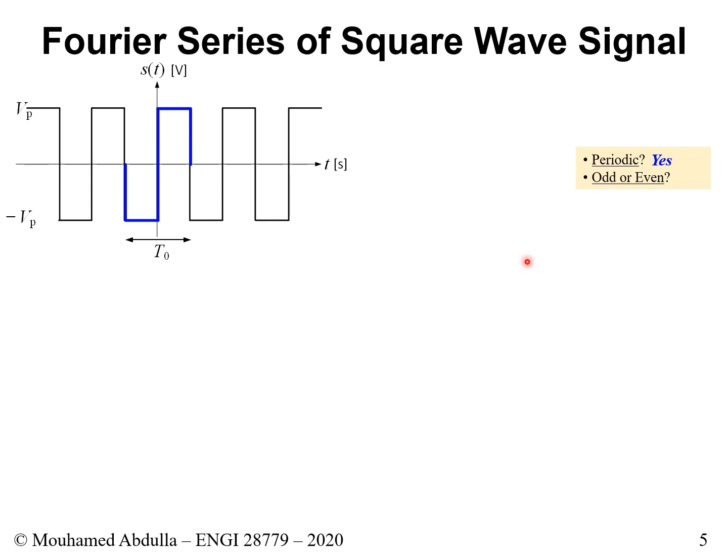Now, maybe we could ask another question. Is this signal an odd or an even signal? So simply by looking at it and while remembering the first slide that we saw in this lecture, this is certainly an odd signal. There's a symmetry with respect to the origin, so it's symmetric with respect to origin, and certainly this is an odd signal, not an even signal.